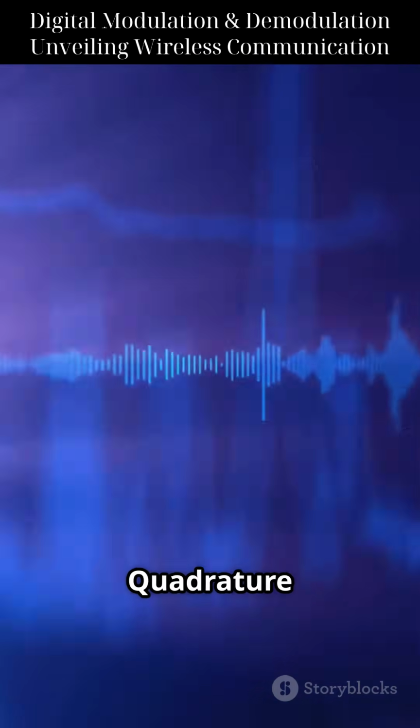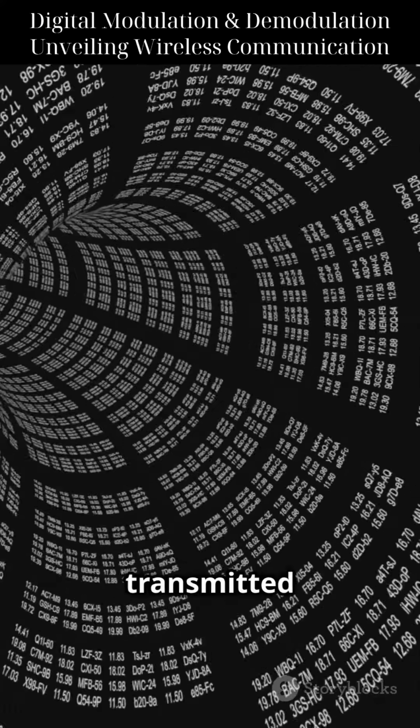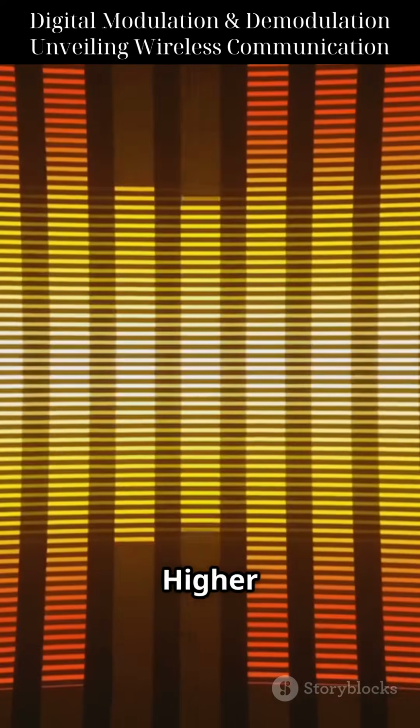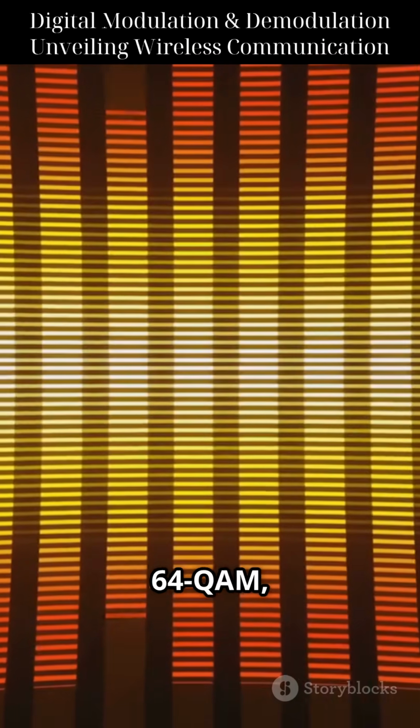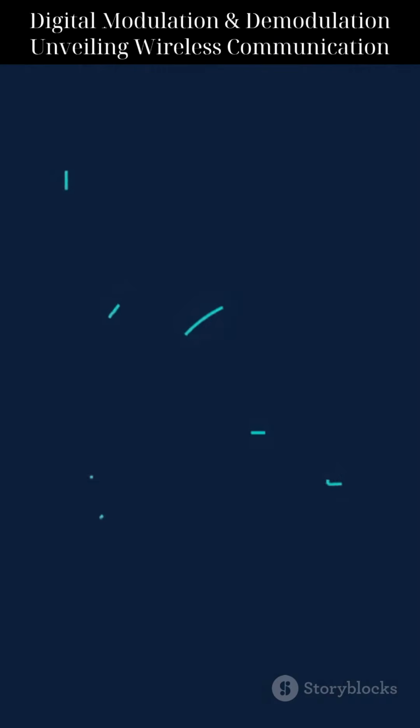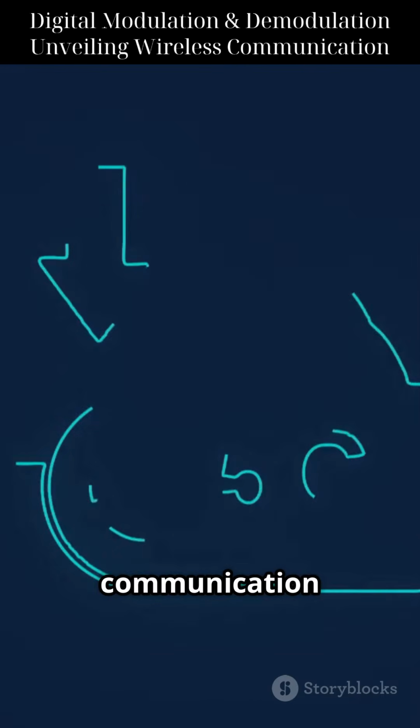Now let's talk about Quadrature Amplitude Modulation, or QAM. QAM is like combining ASK and PSK. It changes both amplitude and phase, allowing more bits to be transmitted per symbol. This means more data in less bandwidth. Higher QAM levels like 16 QAM, 64 QAM, and 256 QAM pack even more data into the signal, making them ideal for modern communication systems.